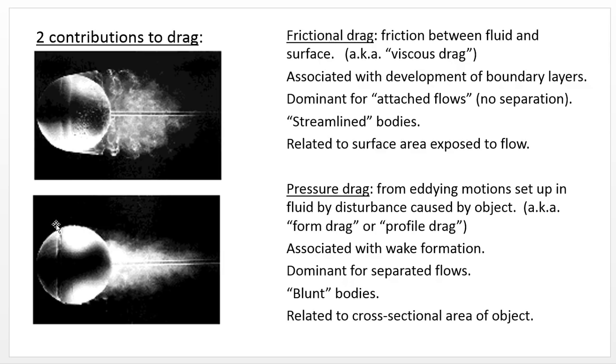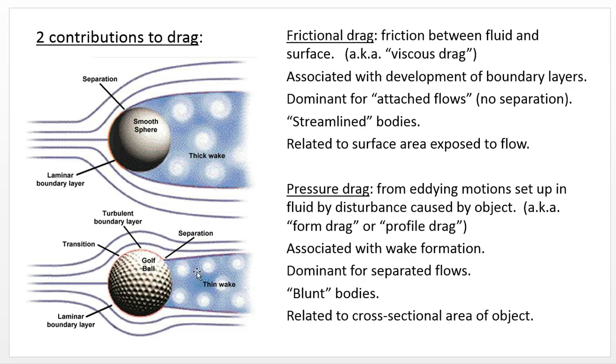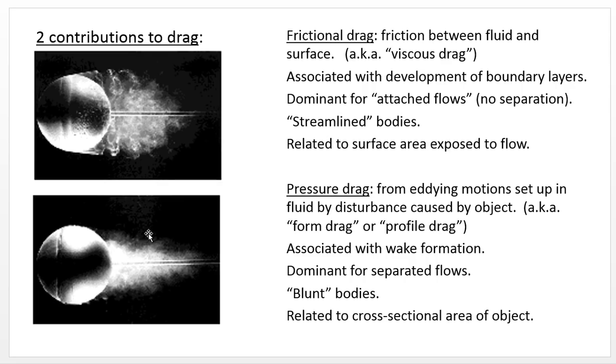You can see with the turbulent boundary layer, the flow separation occurs much later because the momentum can be maintained more in the boundary layer. The pressure that's pushing back this way doesn't cause the flow to stop and separate as quickly as it does for the case of a laminar boundary layer. And so we have a much smaller wake as shown in this actual image behind the object, which is completely consistent with the schematic diagram shown in this previous slide. So that's schematic. This is actual pictures from experiments.